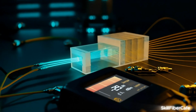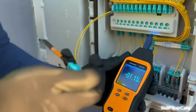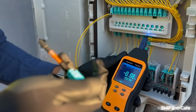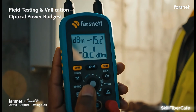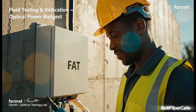Every connector now counts. Technicians use an optical power meter, OTDR, and VFL to verify actual signal levels. These instruments reveal if design math matches the real-world fiber path. During installation, every connection is inspected. If measured loss exceeds design limits, fibers are respliced or connectors cleaned until power restores.